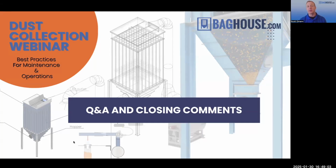The next one that we look at is the dust size and the physical characteristics of the dust. For example, is it a dust that is sticky or abrasive? Is it a dust that's difficult to collect when it's moving through the ductwork or the airstream? Does it tend to stick together? So we need to choose the correct filter that will be able to handle those types of things.